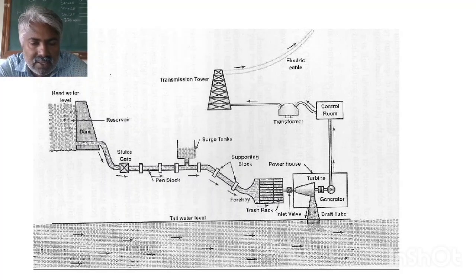It will explode the penstock pipe. So it is not safe. It is not advisable. So for safety purpose, there will be a surge tank. It will have an opening. If there is a backflow of water, it is called the water hammer effect. Because of the backflow, high pressure water will come out and it may explode the pipes.